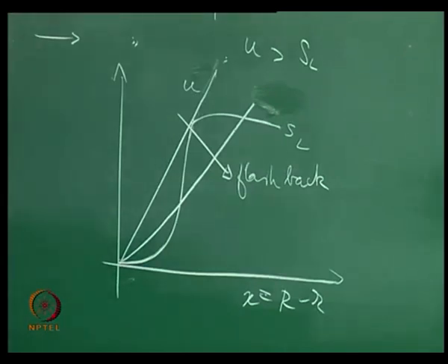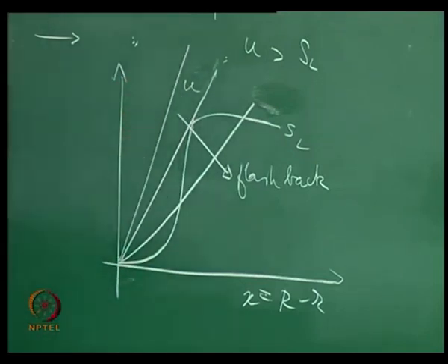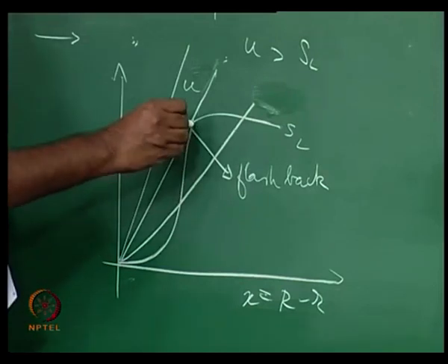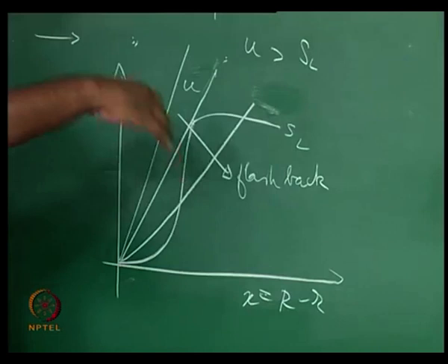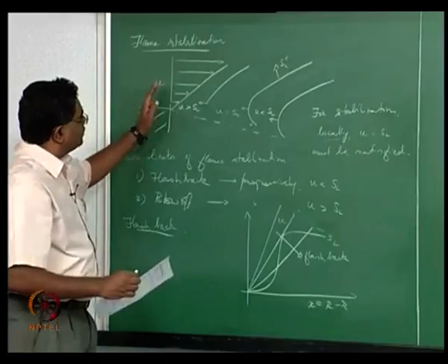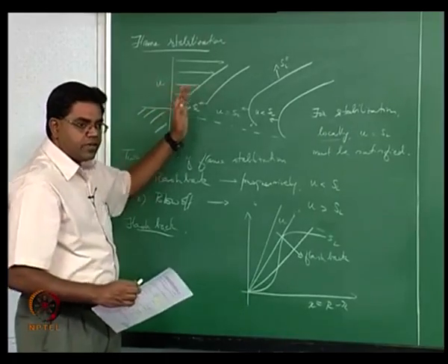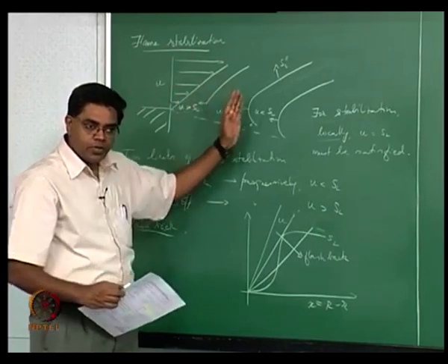On the other hand, if you now try to actually have a higher velocity, then this is the condition for flame stabilization at the rim at the most, and any decrease in velocity is now going to induce a flashback. But if you now try to increase the velocity further, it's going to progressively start to have a flame stabilization a little bit away from the burner, right.